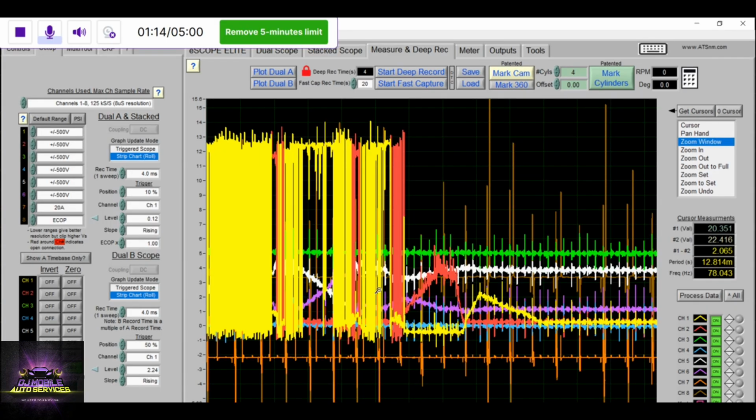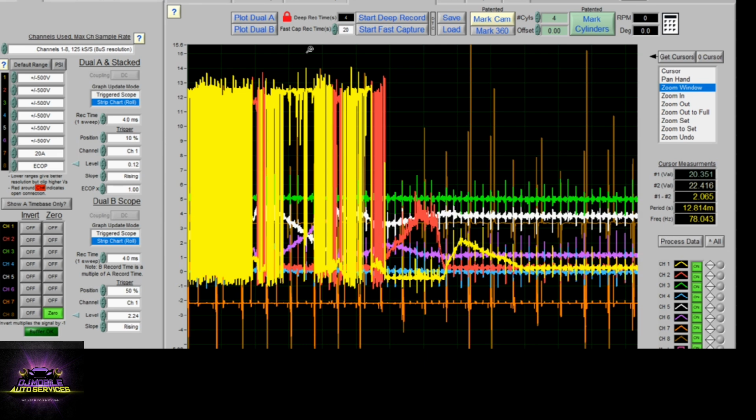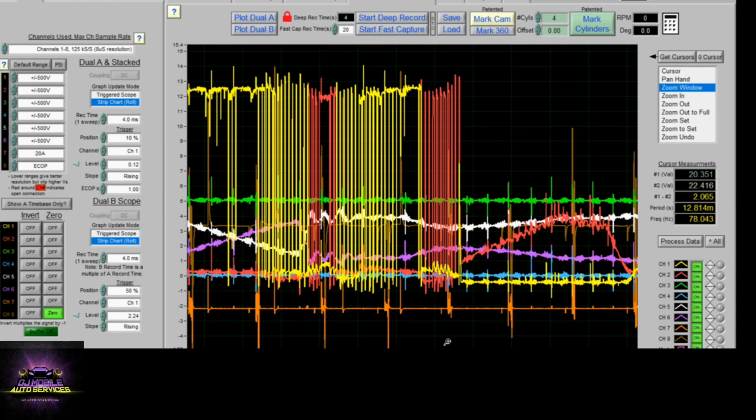Seeing that the Ford uses the H-bridge circuit to control the DC motor within the throttle, we have to look at that as a bidirectional control, where they control the speed and the direction of the motor by reversing the polarity of the voltage across the 4 switches within the throttle. From what I'm seeing here, my power and ground is intact, but my TP1 and TP2 is being affected due to the position of the plate on the throttle.